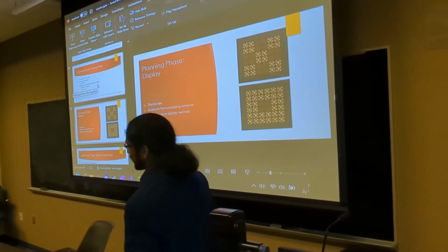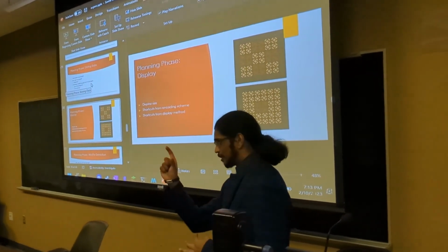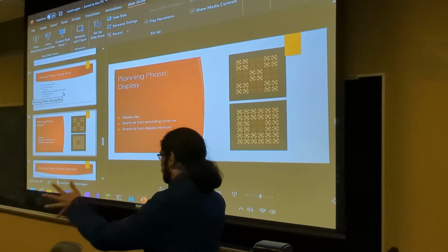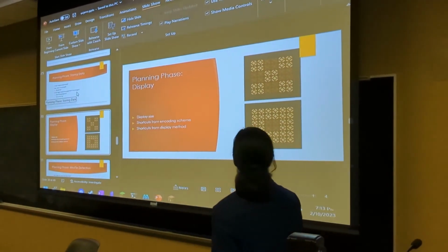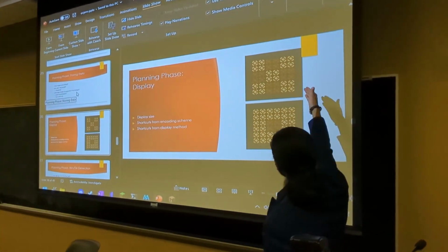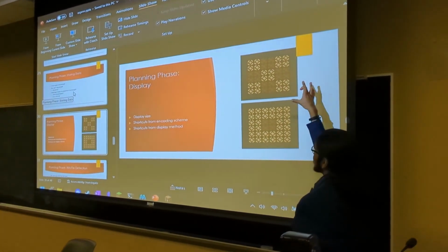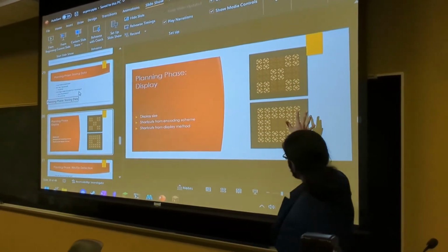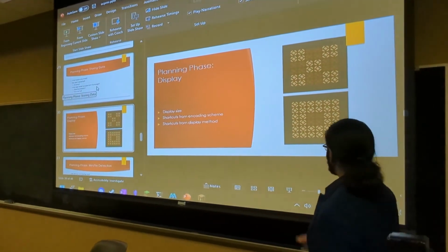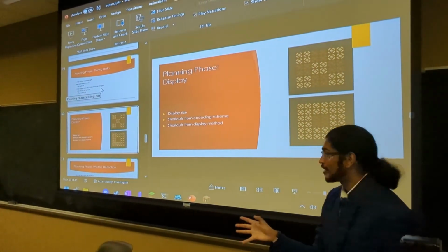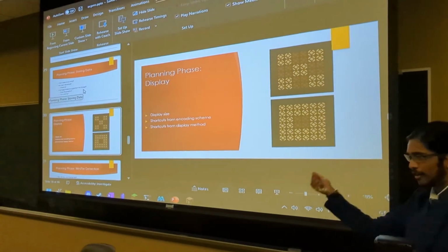Well, we can use something called decoding, where we take a binary number and decode it into whatever signal we need. And we can take advantage of certain things here. First of all, take a look at these two and notice that in either case, the corners are turned on. So we can simply tie these 4 corners to the occupied bit. If it's occupied, turn on the 4 corners.